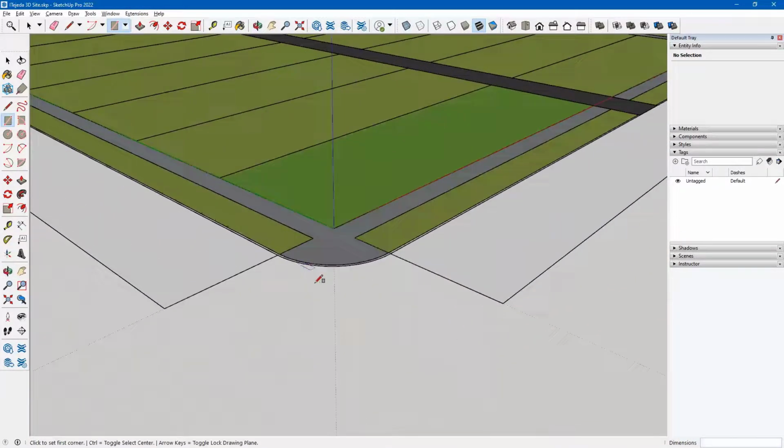And now I need to establish that radius line right here because I'm about to join these two. I call it joining, but I just want to bring them together. Here's what I could do. I could simply draw a line from here across. I'm going to constrain to the green axis by using my left arrow key. I'll click here. And then I'll continue over. And you'll notice it's still not filled in because I need to close it right where I have the arc.